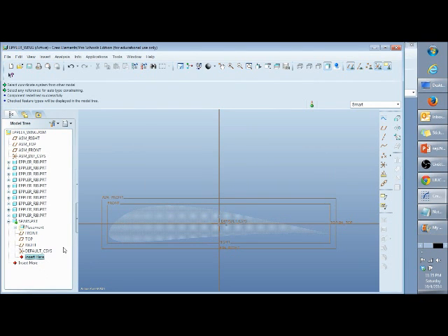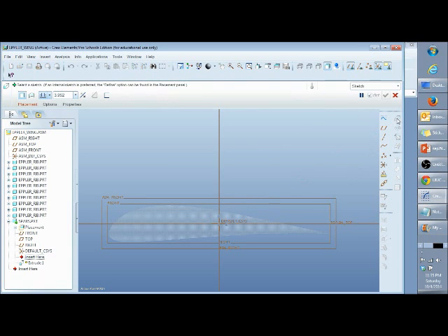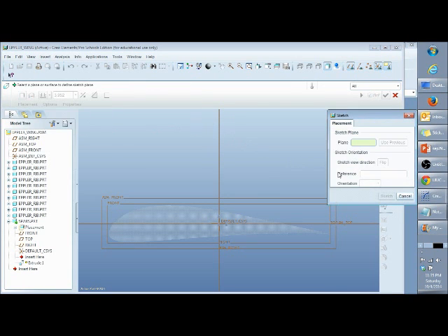So now, since this part is activated, you are modeling within the part more so than the assembly. So go ahead and hit the Extrude tool like I just did. It might appear in a different location on your computers. This is just the layout that mine downloaded with. So go ahead and hit define, select the plane.